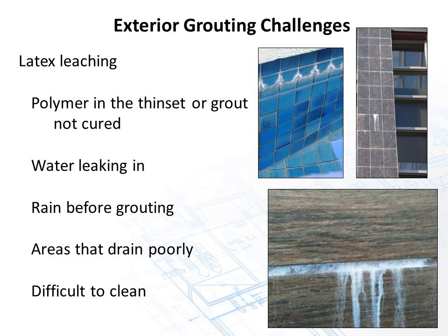If the parapet cap's left open, if the roof leaks into that area, I've seen some fast food stores where the roof membrane runs in behind the tile. All that will fill up with water, and the only way for that water to get out is through the grout joint, taking some of the latex with it.